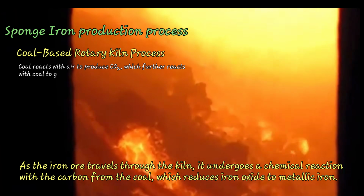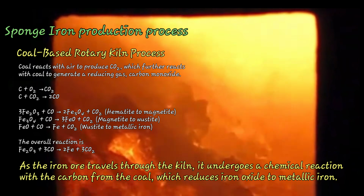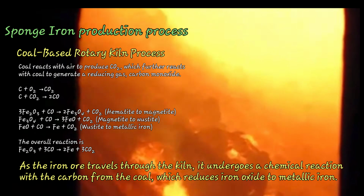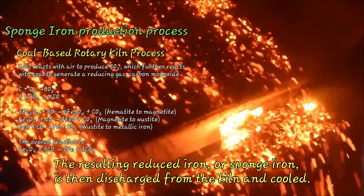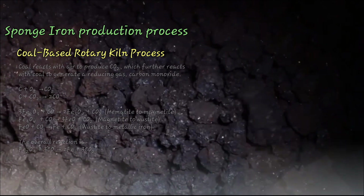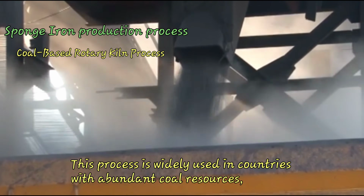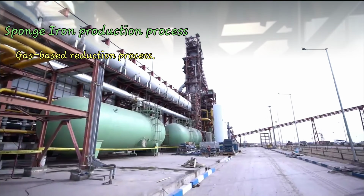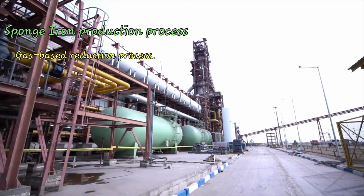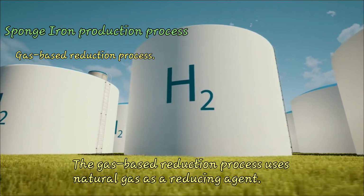As the iron ore travels through the kiln, it undergoes a chemical reaction with the carbon from the coal, which reduces iron oxide to metallic iron. The resulting reduced iron, or sponge iron, is then discharged from the kiln and cooled. This process is widely used in countries with abundant coal resources, as it offers a cost-effective way to produce sponge iron. Gas-based reduction process. The gas-based reduction process uses natural gas as a reducing agent.